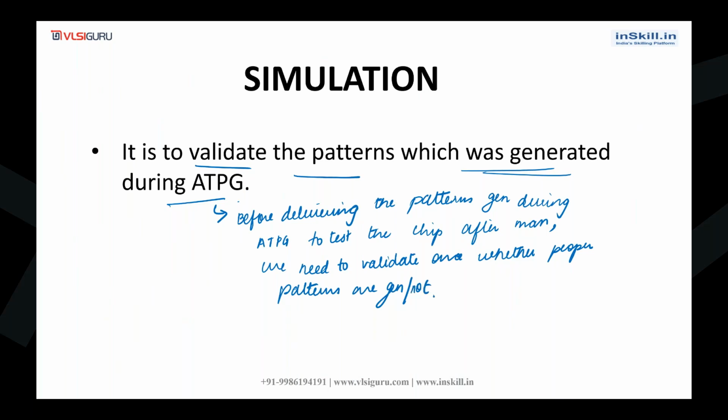So this is what is called simulations. It is to validate the patterns that were generated during ATPG. Before delivering the patterns generated during ATPG to test the chip after manufacturing, we need to validate once whether proper patterns are generated or not. That is what is called simulations.